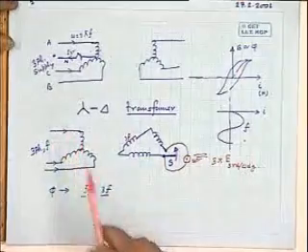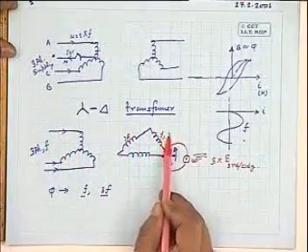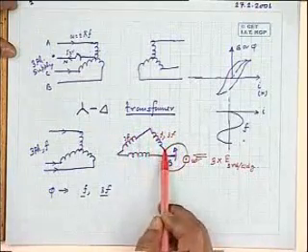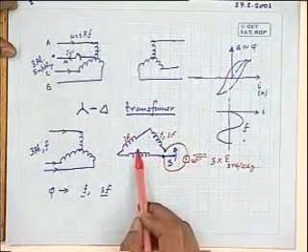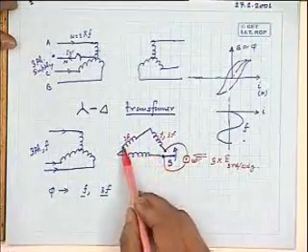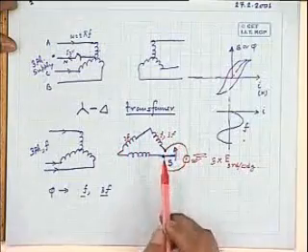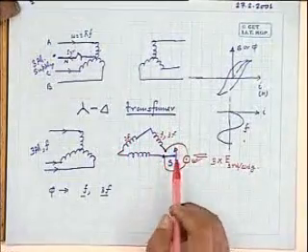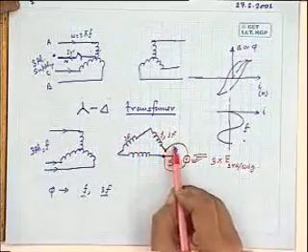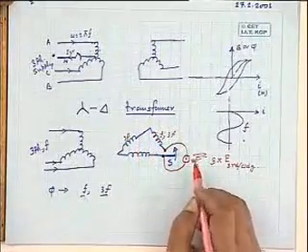Therefore, in a star primary side, delta secondary side, each winding will have fundamental frequency, third harmonic frequency. But the sum of all the fundamental frequency voltages will be 0. But third harmonic voltages will be co-phasal in nature. Therefore, their algebraic sum, it amounts to that. 3 times of that will come across the voltmeter. Now, we find that in this circuit, there exists a third harmonic voltage.